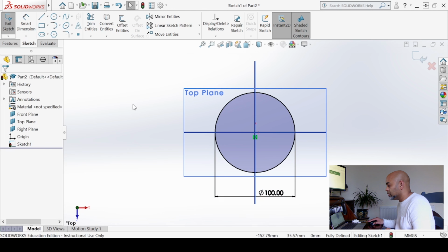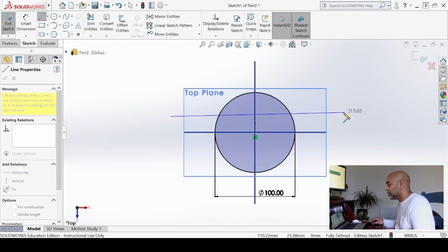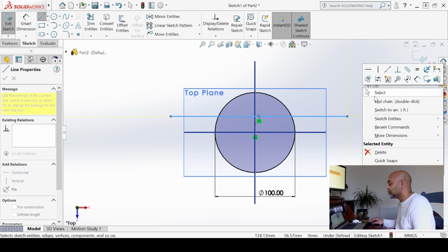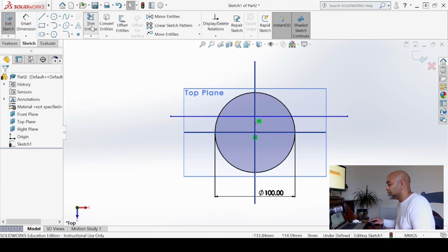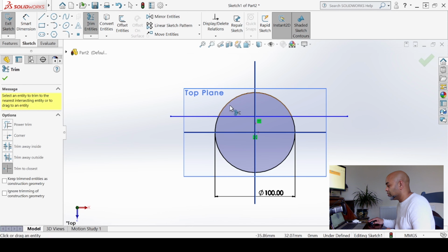What we have also done in addition to this is we have managed to remove parts of the sketch by using, let's just say, other entities, so some sort of subtractive operations. So I can use the trim entity command to get rid of that bit if I'm not interested in that anymore, so on and so forth.